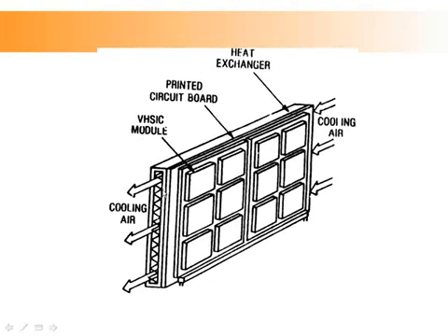Another design is what is called a heat exchanger that is sandwiched between boards or on a single board. The heat exchanger becomes part of the board, and here you can have air or you can have liquid cooling. So this is another design. Each one of these is different. When you go to these heat exchanger designs, you can carry a lot more heat. You can dissipate more heat when you do those.